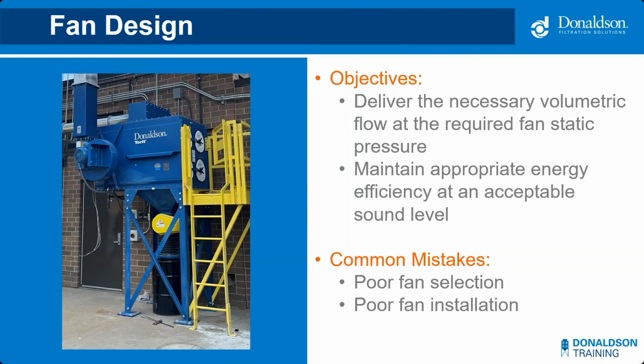And secondly, the fan you select must be able to deliver the desired static and airflow with the appropriate energy efficiency and acceptable sound levels. For example, non-material handling fans located on the clean air side of the collector are more efficient than material handling fans on the dirty air side of the collector. Fan challenges generally fall into two categories: poor fan selection and/or poor installation.